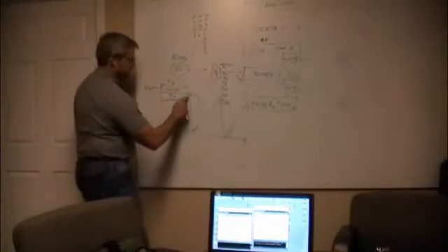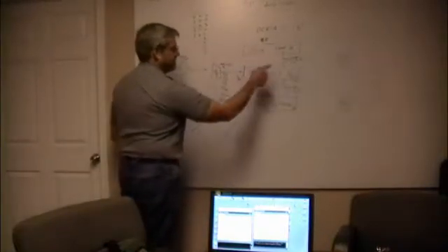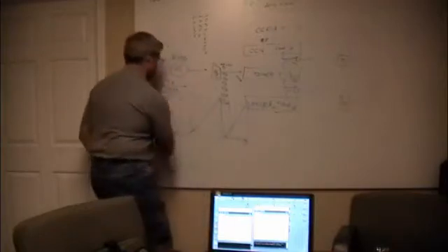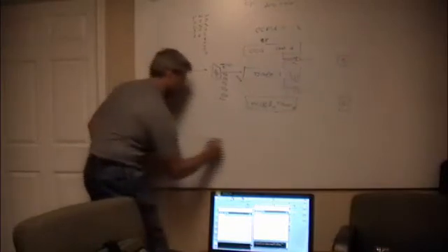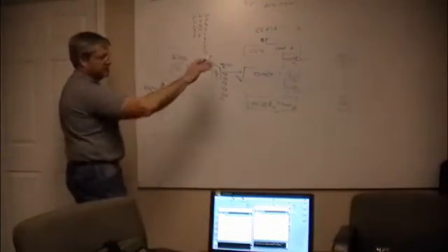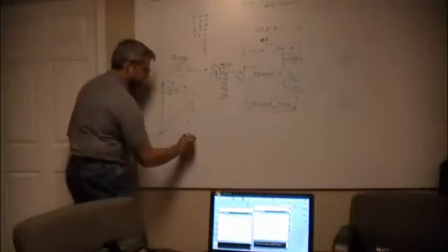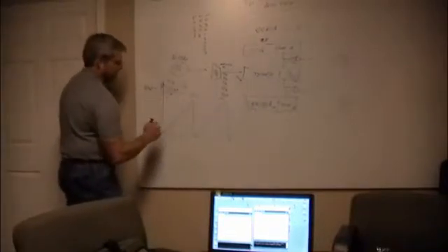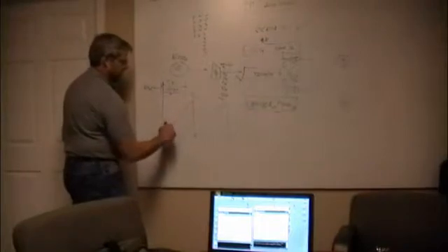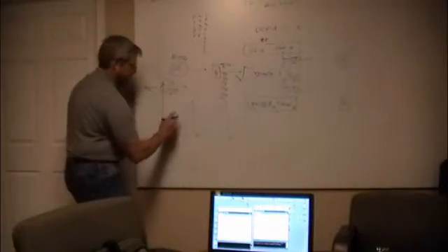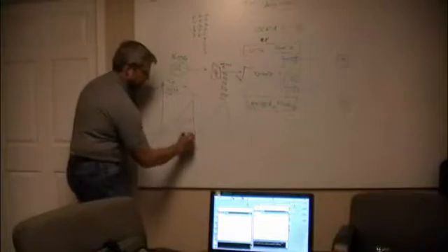So right now if I say reset the timer when it hits 8K, now it only gets to, let's redraw it. So if I had it at 16K or I didn't do anything and just let it run and run and run, I would get this, right? With that being 65,535. So if that's 16K, then 8K would be right about there. So now if I set that to 8K, what's going to happen is this. And now you just see I doubled my frequency.